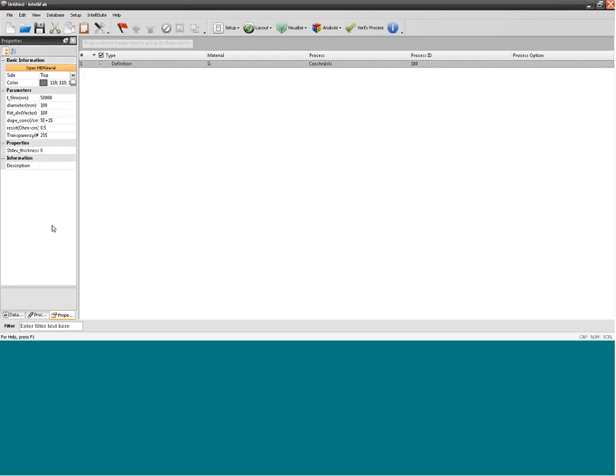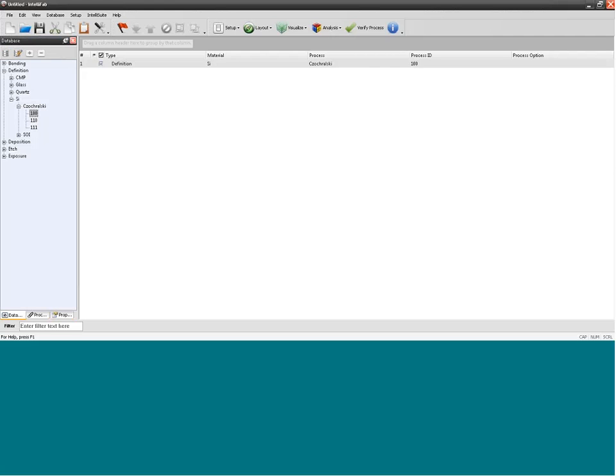And you'll see that we've defined our first step, which is a silicon wafer definition with 100 orientation. When we add the process step into the traveler, you'll see that the process properties are listed over here now on the left-hand side of the window. For each process step that you add into the traveler, you can set up some of the different process parameters for that process step. In this case, the most important thing that we would be defining is the thickness of our silicon wafer. We would just input that value right here. Looks like it's set up to be 50 microns right now.